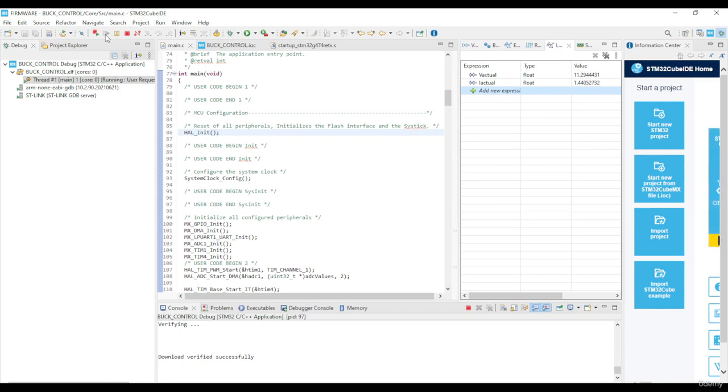If you want something more stable, we're dealing in control state. If you want something for a display, then I would suggest extreme averaging, like over 1,000 points at least, and then you would have much more stable values. But in this case, we're dealing with control, and we can expect that this will be compensated for in the control. So that's just a brief overview as to basically not panic when you see readings like this. You can see it's hovering between about 10.8 and 11.4.